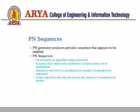PN sequence. What is a PN sequence? A PN generator produces a periodic sequence that appears to be a random sequence of binary ones and zeros. PN sequences are generated by an algorithm using some initial value called the seed. The sequence is typically not truly random but will pass many tests of randomness. Such a generator is referred to as a PN sequence generator. Unless the algorithm and seed are known, the sequence is impractical to predict.